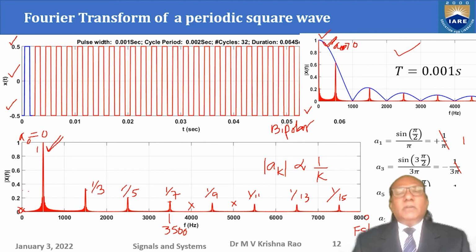Whatever I have done so far, they are all discrete time signals. Many people confuse this, because just because the plot is continuous, you should not think the values are continuous. The digital computer generates only discrete values, and you join the tips of these discrete values so that you get a continuous curve. It is the magic of the graphics package, not that the values are actually continuous.